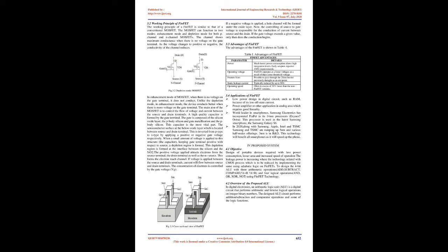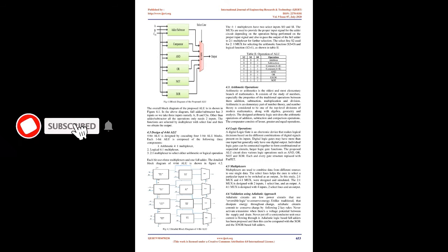They have also simulated the logically equivalent static CMOS RCA circuit to compare the energy saving of adiabatic and non-adiabatic logic circuits. In the clock frequency range from 25 MHz to 1 GHz, the proposed PCG gives a maximum conversion efficiency of 56.48%. This research work shows how the design of an efficient PCG increases the energy saving of adiabatic logic. Adiabatic logic circuits offer significant reduction in power dissipation when compared with static CMOS.